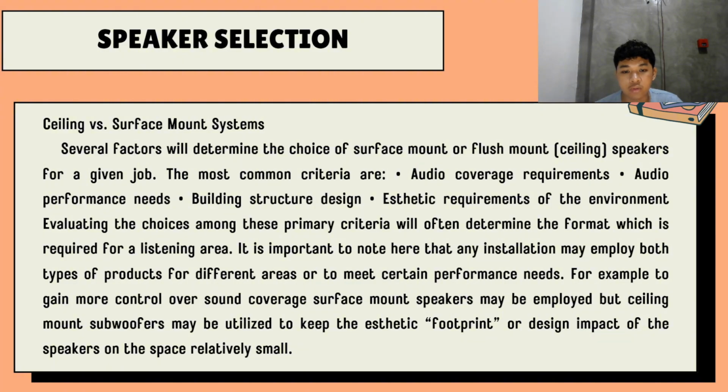And it's important to note here that any installation may employ both types of products for different areas or to meet certain performance needs. For example, to gain more control over sound coverage, surface mount speakers may be employed, but ceiling mount subwoofers may be utilized to keep the aesthetic footprint or design impact of the speakers on the space relatively small.